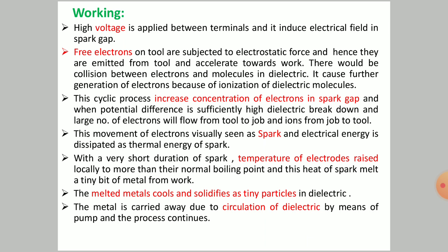A high voltage is applied between the terminals and it induces an electric field in the spark gap. The free electrons on the tool are subjected to electrostatic force, and hence they are emitted from the tool and accelerated towards the workpiece. There would be collisions between electrons and the molecules in the dielectric. It causes further generation of electrons because of ionization of dielectric molecules.